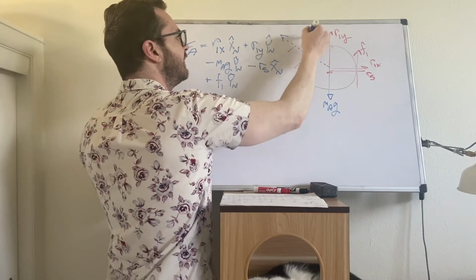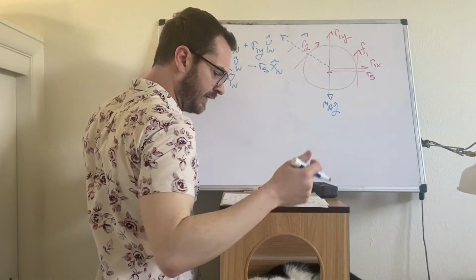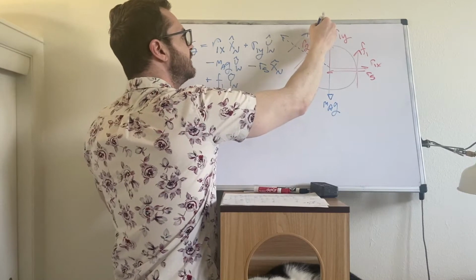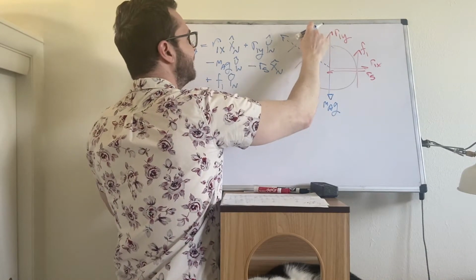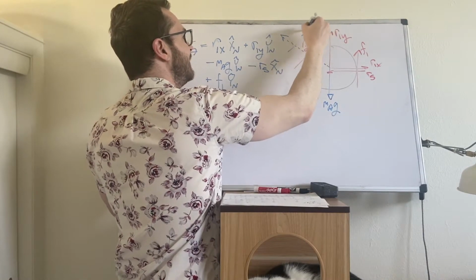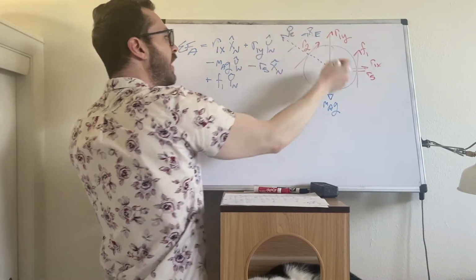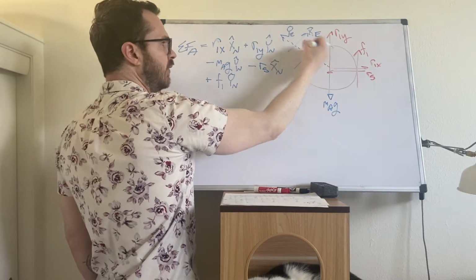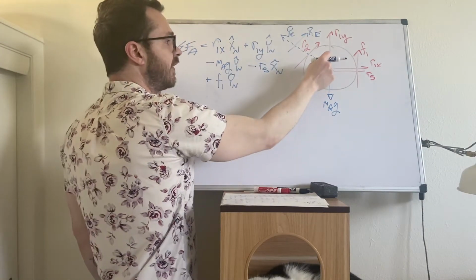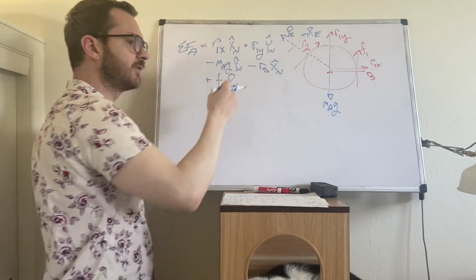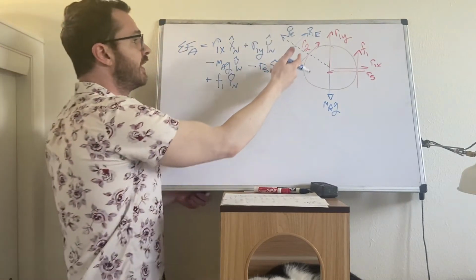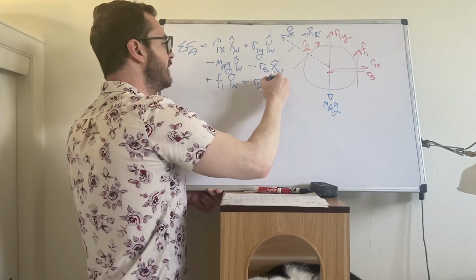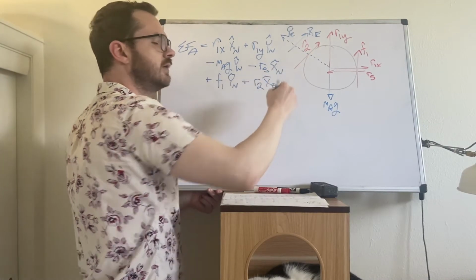Let's see, I defined it as the E frame. So we had bodies A, B, C, D. This direction is X, nope, not XD. This is direction XE, and the radial is YE. And of course, this direction, YE, is going to point from the center of disk A to the center of disk B. So we can use that then to define R2. We can say R2 in the XE direction.